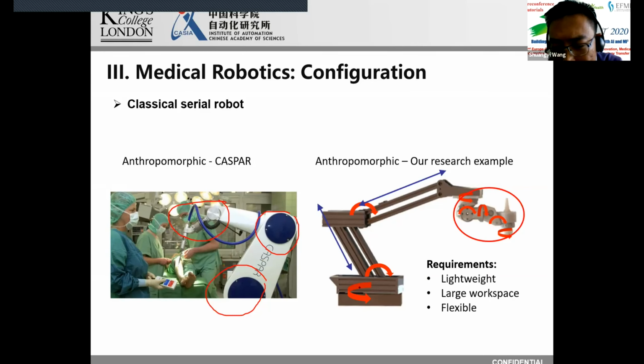So the characteristic of this arm is that it is very lightweight, and we have 5 degrees of freedom embedded into a very small area. It's only about 20 centimeters, and the total weight of these 5 degrees of freedom is only 2 kilograms, and they are all 3D printed, which means if there's any failure of the control electronics or sensors, there will be only 2 kilos on top of the patient's body.